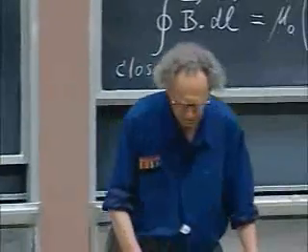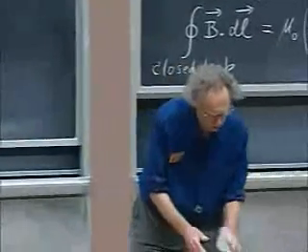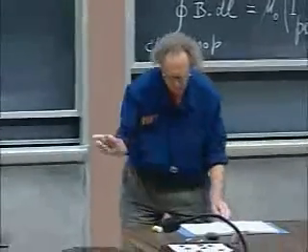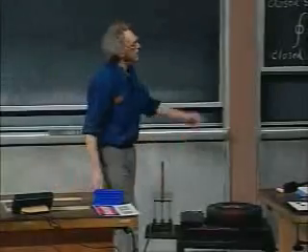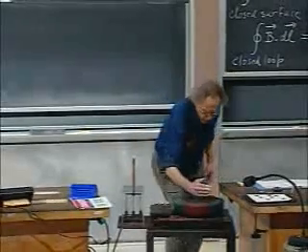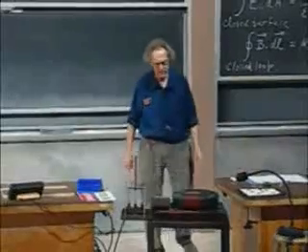And the first thing I'm going to do is show you that unit that we have here, which are the coils that I described, through which we are going to run the three-phase current. I must get my lights right. There you see it. Coils are wound in a very strange way. After class you can come a little closer. And so in here you would have a rotating magnetic field. We use 60 Hertz. It rotates around 60 times per second.